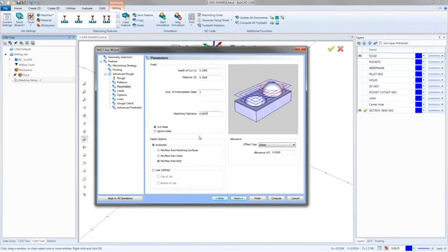Right here's the machining tolerance. That's just the quality of the tool path. That's pretty much, if the tool path is running in a straight line, the tool's allowed to deviate a 1/2 thou in either direction. It's our tolerance that we build in. If you change it from 5 to 1, it will take longer to calculate, but the tool path will be better. So there we go. I'm going to leave it there.